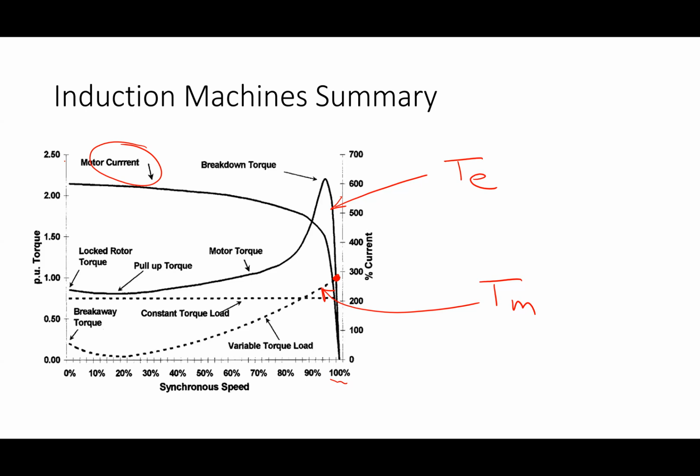All right. That leads to something we call an inrush current, which is to say that when I start the motor and connect it, there's a very high current that is, quote unquote, inrushing into the motor to get it started. That high current's a good thing because it helps the motor accelerate faster. You'll notice here, not to say there's a hard and fast value on that, but at 0 speed, the current is on the order of about 600% of rated. In other words, it's about 6 times higher than its rated value.